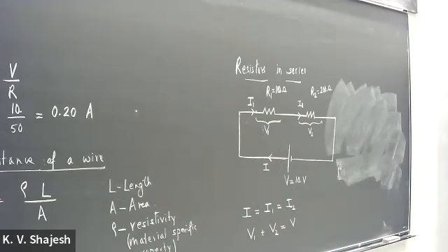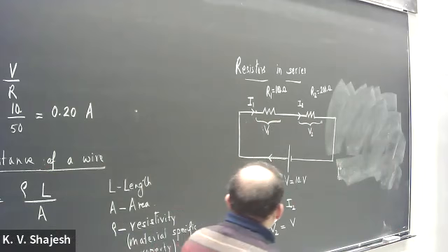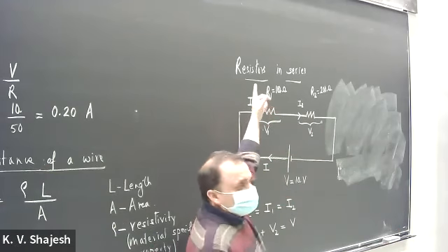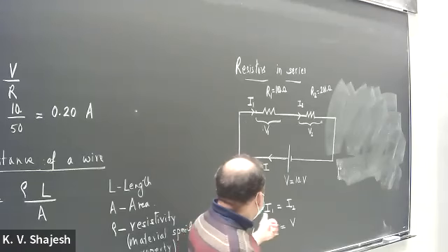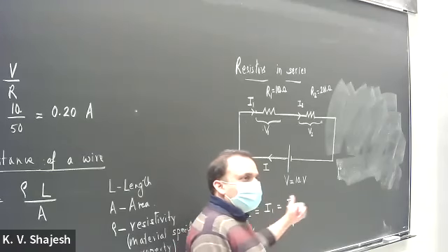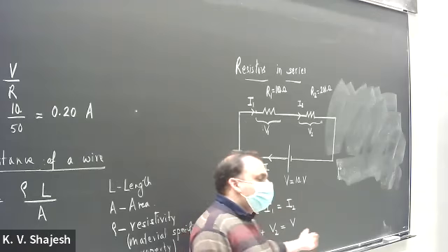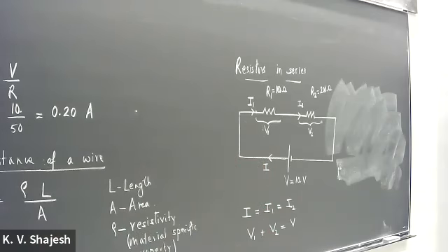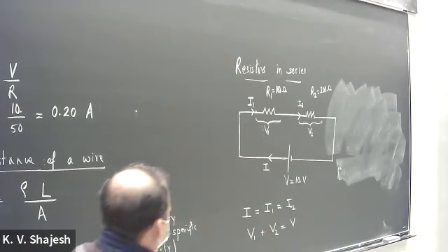These are very similar arguments we used in capacitor, but if you were to look into your capacitor notes, it's exactly the opposite. In the case of capacitors, when they were in parallel, we had charges that were the same and the voltage distributed. So capacitors in parallel pretty much behave like resistors in series as far as the mathematics goes.